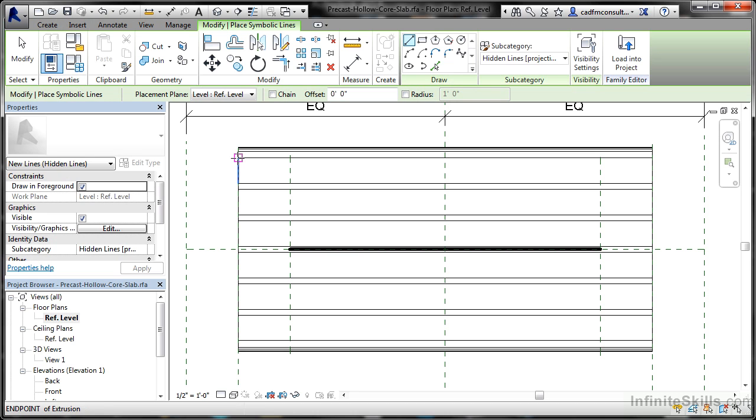So we'll start there, click, drag a line, and click again. So there's one line there. We then click again. There's another line here, click, drag a line, and we click again. Make sure you get the snaps each time. We click, drag, and we've got to draw 12 of these, and it does take a little bit of time. Just be precise, take your time, be methodical with the snaps. The snaps are very important because they will display whether the lines are horizontal or not. As long as you're snapping to endpoints and moving horizontally, you can see those lines going in. Just make sure you get the right snaps.